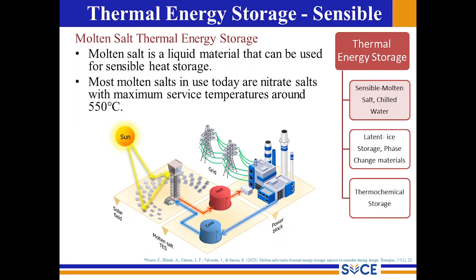It consists of concentrated solar plants. The solar radiation is reflected with the help of reflectors onto a central point where the molten salts are recirculated. This causes absorption of the solar energy into the molten salt, resulting in its heating. It is used at temperatures around 500 degrees Celsius.